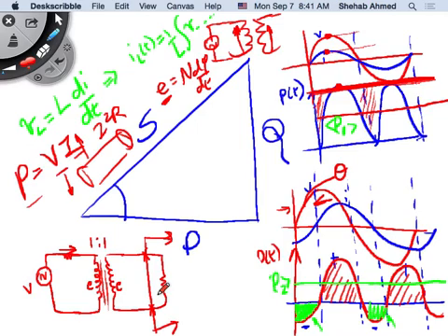So it basically looks like an inductor to my source, right? So it's going to cause the current to be, if you were drawing this current at 90 degrees from your resistive load current, for example, if you remember, when you were drawing the magnetizing branch and the core loss branch, each one of them was 90 degrees apart, all that kind of stuff. You remember that back then? But anyway, the current that's coming in here, if there's no load, will be a small amount, and it's basically used to set up the magnetic field to create this back EMF voltage, right?